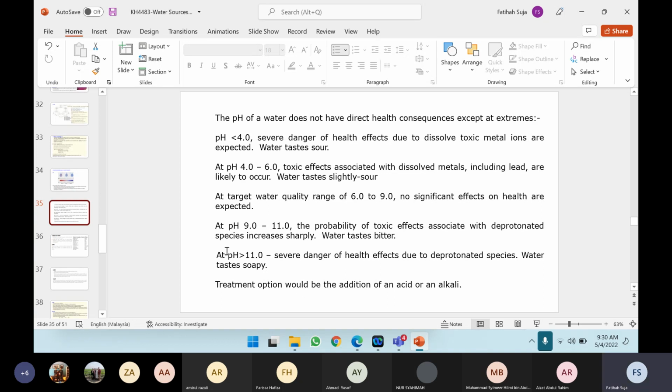Only HCl will work with this pH greater than 11, because if you use a very mild acid, you need to input so much of this acid that usually it is not economical. So let's say if you have pH greater than 11, I would suggest that you try to find something natural, maybe a natural coagulant.